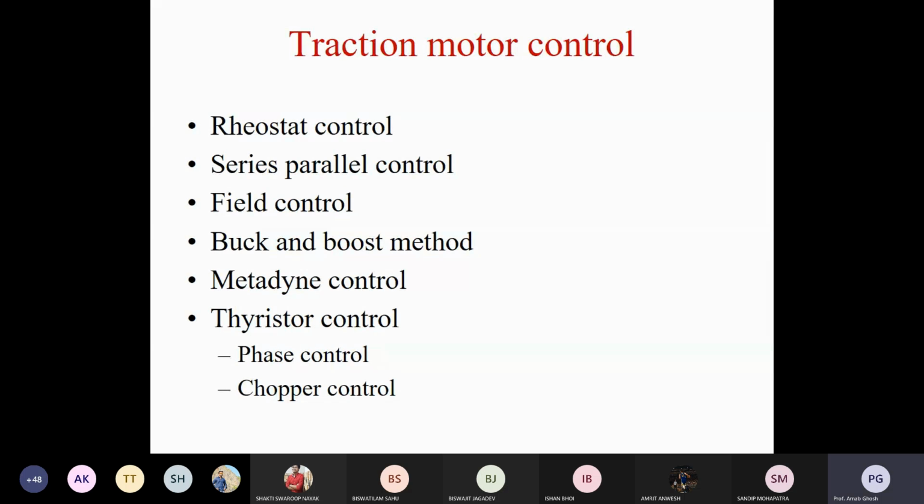Now, instead of this type of machine, we are using power electronics converters, especially inverter control. For harmonic mitigation, normally we change winding configurations, like fractional order winding and distributed winding, for eliminating harmonics. The same type of idea we also use in inverters to eliminate the harmonics. So now power electronics converters are in our studies, and that's why old machineries are obsolete.